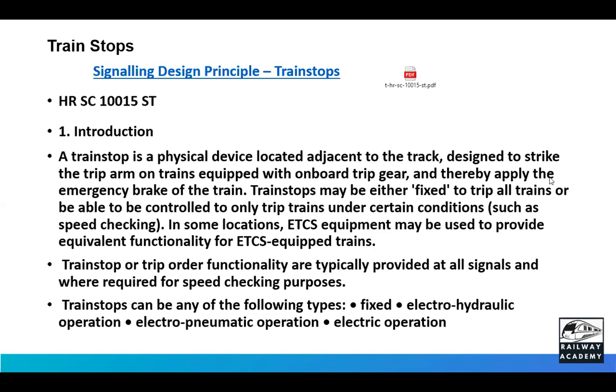There are also two types of brake applications. If the red signal is passed, emergency brake application will take place. If it is an intermediate train stop for reduction of the speed, then it can trigger a service brake application. Like that, different train stops trigger different brake applications, just to take care of the driver's mistake.